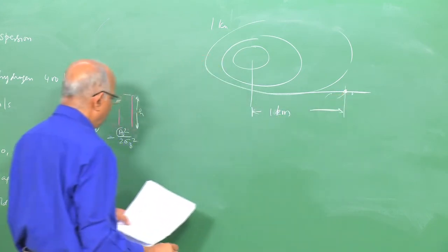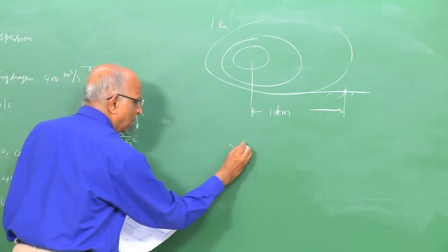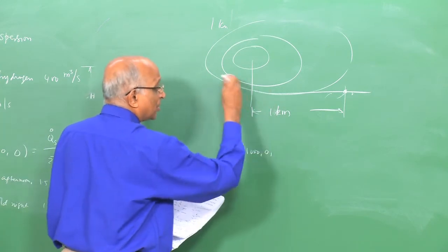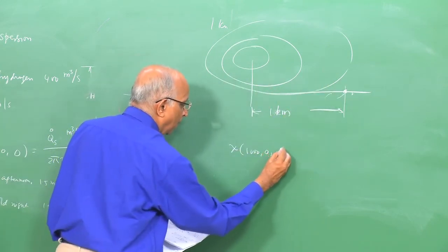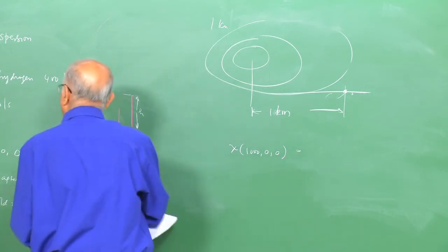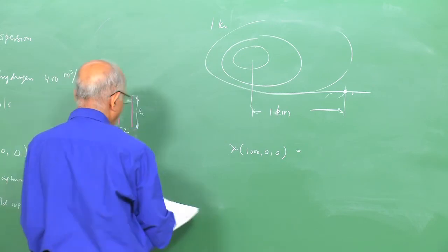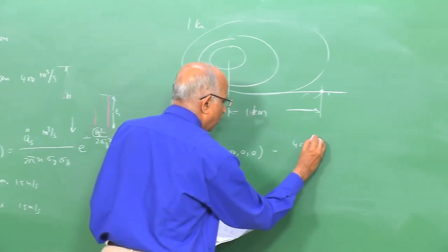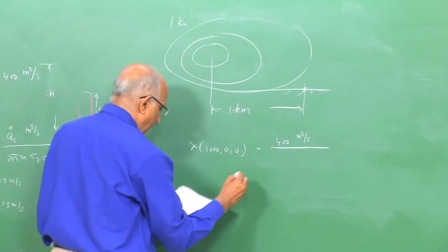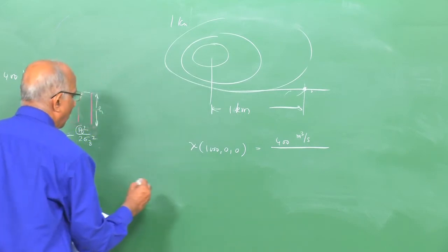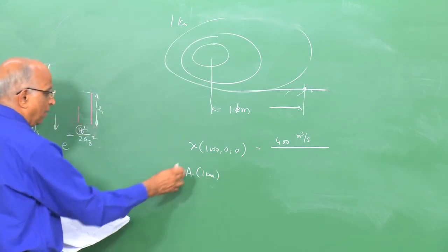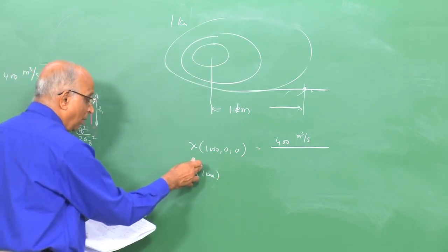At this particular point, therefore, I calculate the concentration at 1 kilometer away, that is 1000 meters. For y equal to 0, I am just considering along the wind direction, along the surface of the earth. This gives me a value. I said q dot s is equal to 4000 meter cube per second, volume is specified, and if I calculate the value at condition A for 1 kilometer, I use the formula given for either rural or for urban area.